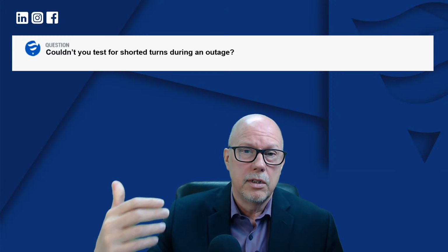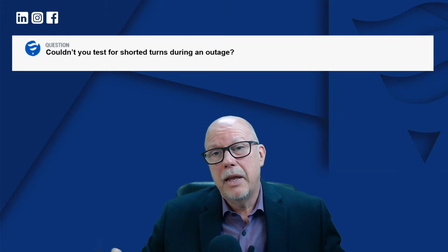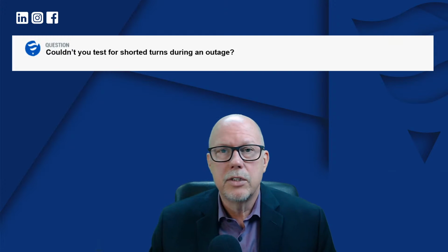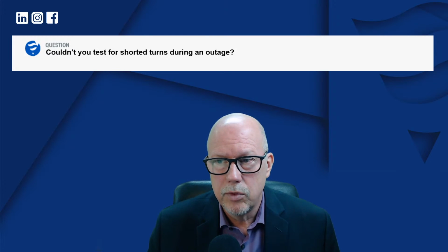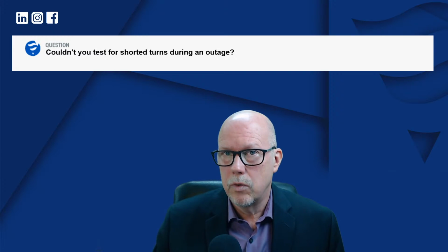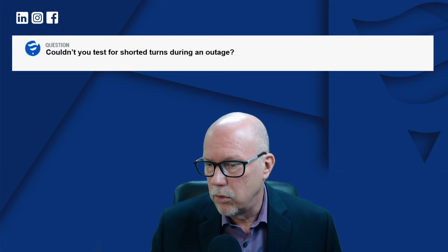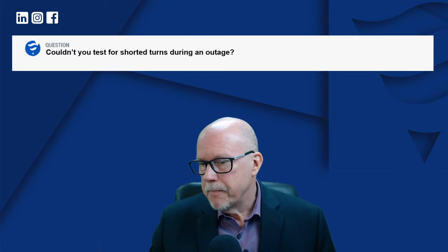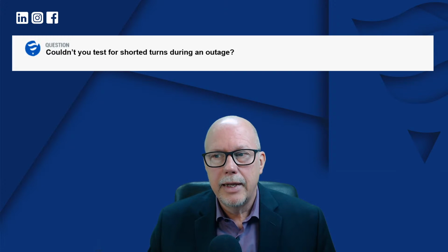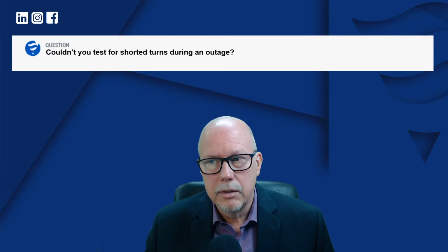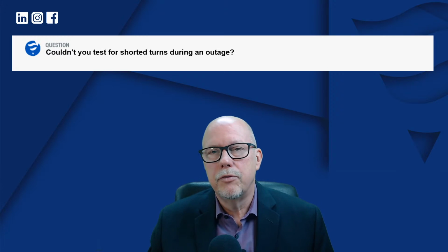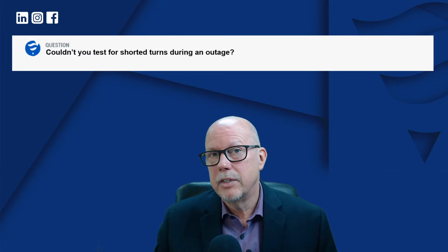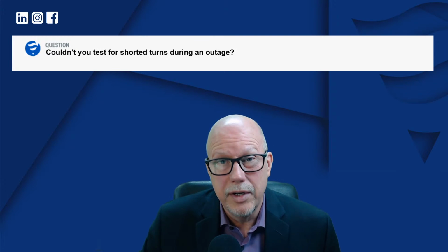And in addition, the coils are hot, they expand. The short might show up there. So there are many reasons why a shorted turn, which exists while the unit is in operation, may not show up stopped and cold. Doesn't mean you shouldn't do the test. It just means that you might do the test and find nothing. So the idea of having a system that is online, at least if you do have these issues, it may tell you, or it may confirm that you have an issue. It might even tell you some indication as to where it is.